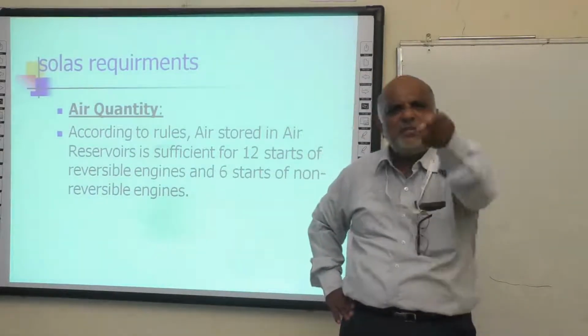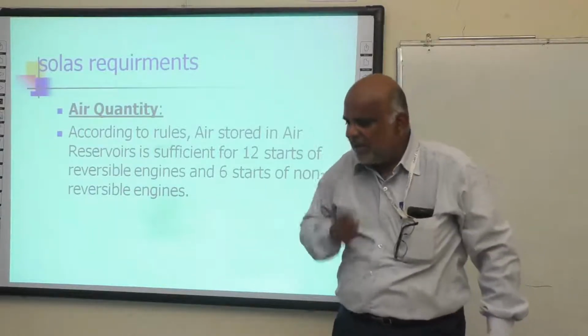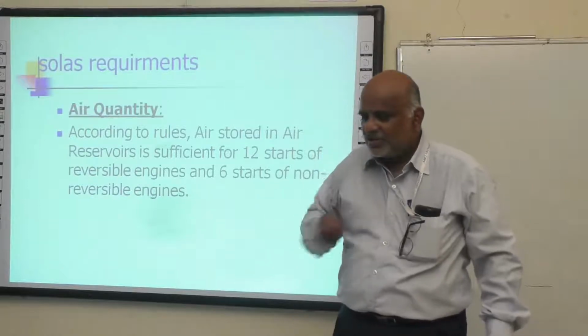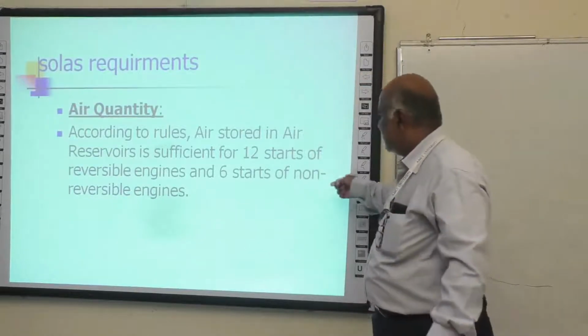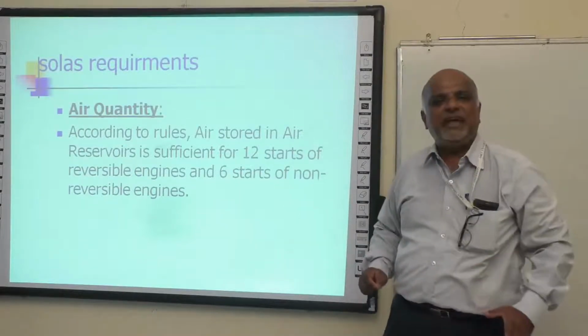What is this reversible engine and non-reversible engine? An engine which rotates only in one direction is called a non-reversible engine. You should have minimum 6 starts of air.